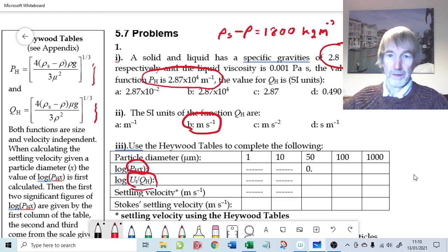Okay, so what we're doing here is comparing these two rows. The takeaway message is that we've got these two rows here that are settling velocities, both in meters per second. However, this one is solely due to Stokes, so we're going to apply the simple Stokes settling equation to work out these settling velocities, and quite frankly they should be right for relatively low sizes and therefore relatively low settling velocities. But Stokes' settling equation is not going to be valid when we have significant form drag. So we're really expecting these two to be poor values, whereas just here we would expect a very similar value, whether we apply a technique that only uses viscous drag, which is Stokes, or a technique that is valid for all Reynolds numbers and includes all the form drag as well as the viscous drag. So we kind of expect these two to be similar.